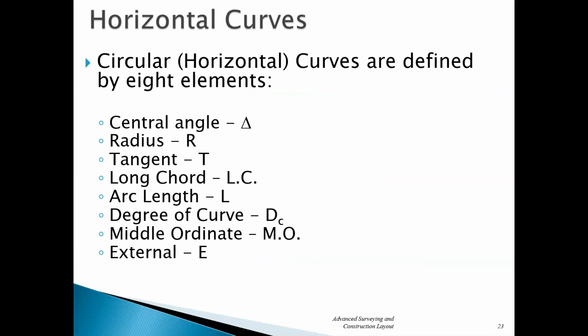Okay. So when we look at a circular arc, circular defines the geometry, but when I say horizontal, I'm defining the plane it's in. So you could theoretically call this a horizontal circular curve. A lot of people just use the term horizontal curve, and what they really are talking about is this circular. That's kind of a bad thing to say, but we all do it. Everybody just calls them horizontal curves, but in reality, what we're really saying is it's a circular curve in a horizontal plane. So curves are just arcs, okay?